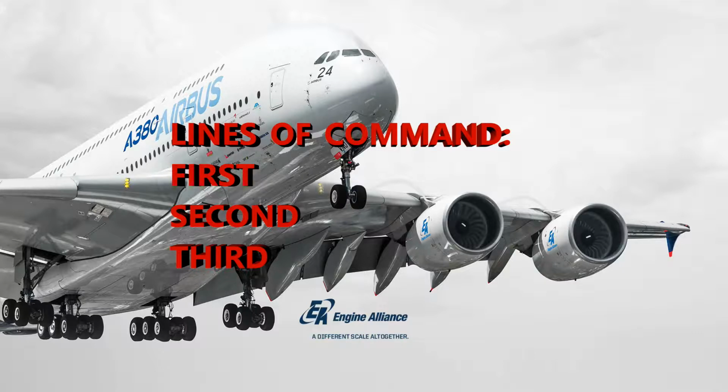And the computers are going to be telling the electrical power distribution center system to release the track locks, because the thrust reverser cowls are in a locked position until they get deployed. So those locks have to be obviously released so that the cowls can be deployed.